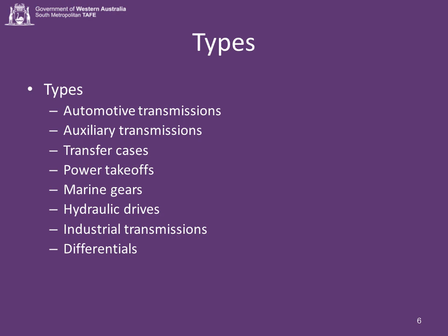or they may be an integral part of a driven component. A differential. This is a set of gears with three independent rotating members with a speed and torque component. What this allows is for one input and two outputs, and for the outputs to go at different speeds while still providing torque. The automotive differential is the best example. The second application type has two inputs and one output.